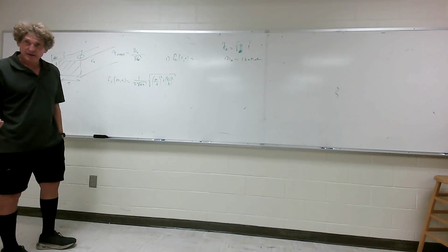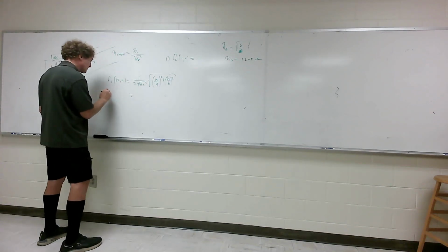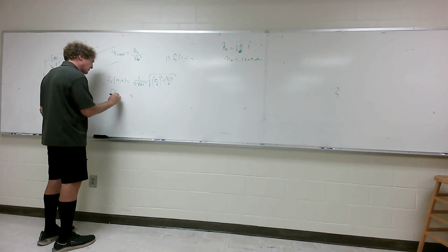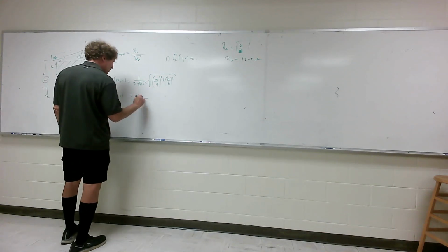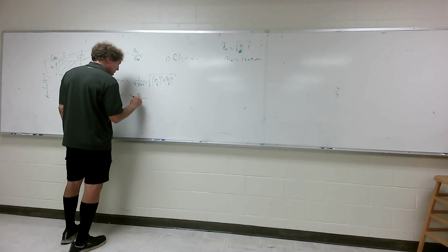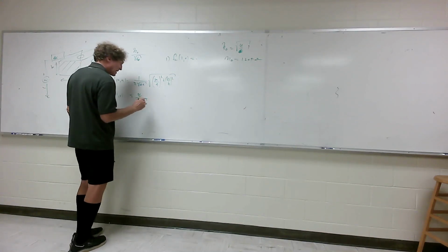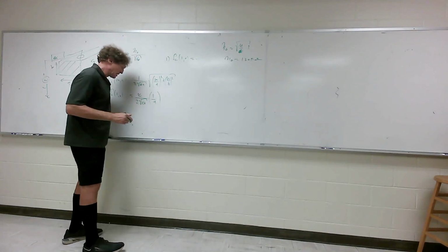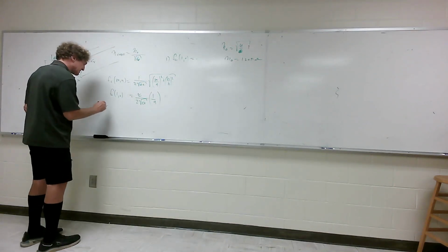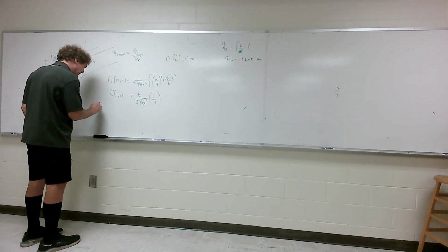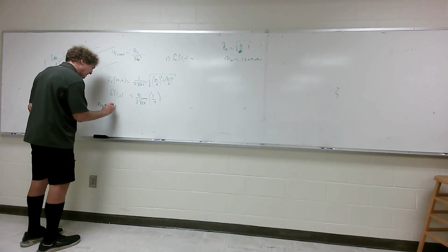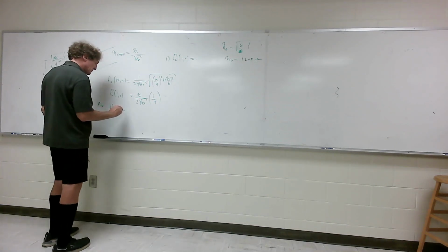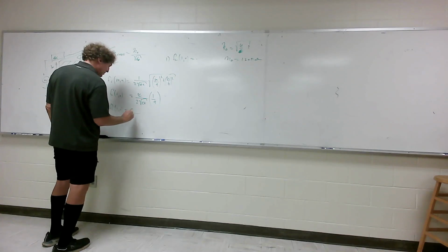Right? Remember this? So this is really going to be, for the cutoff frequency for the 1-0 mode, c over 2 square root of epsilon relative, and then you're going to have simply times 1 over a. And if it's free space, if you're talking about air in the guide, then fc 1-0 is simply equal to c over 2a, right?